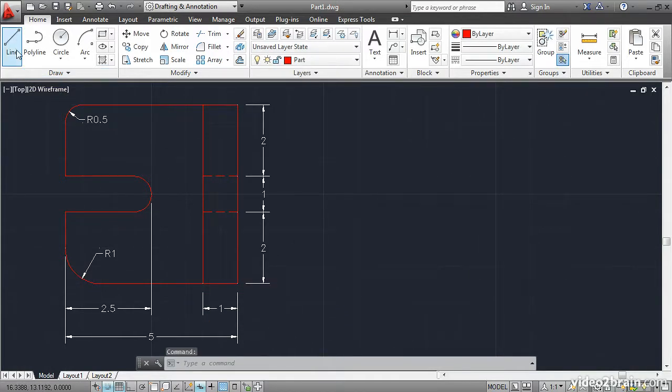Go up to the Line tool and click it, and notice that as you move the cursor in the drawing window, it jumps from one point to another. This is the effect of snap. Move the cursor over here horizontally from the red line, and click at this major grid line, which is the brighter gray line on the screen.